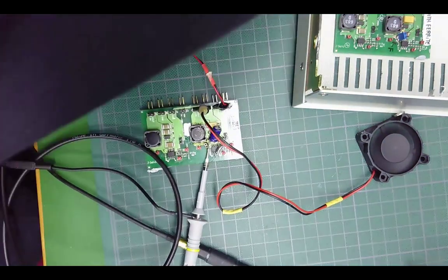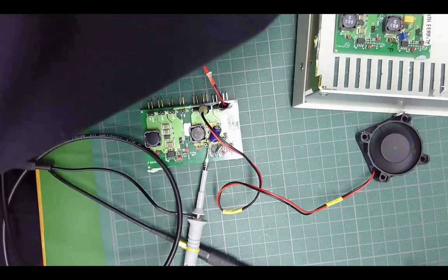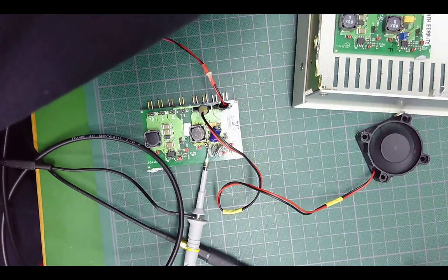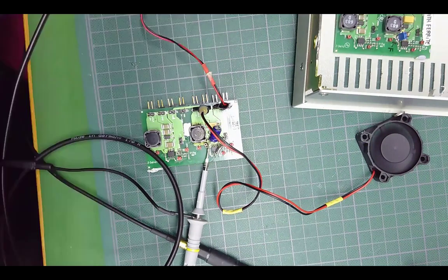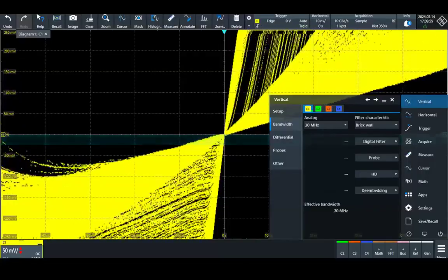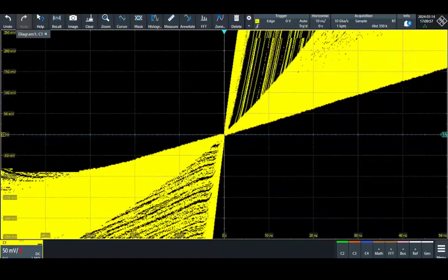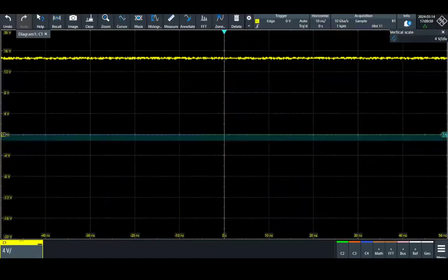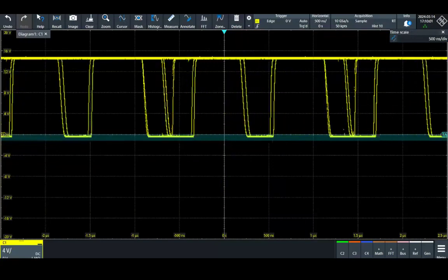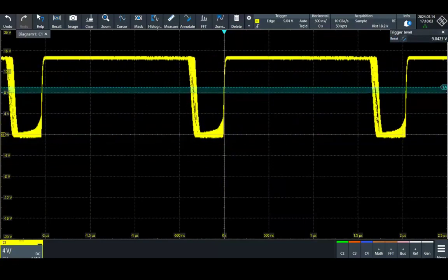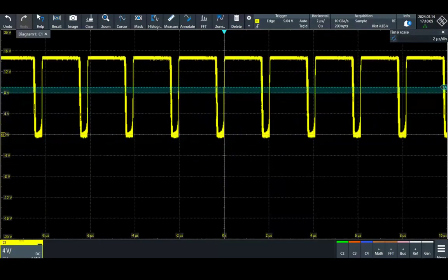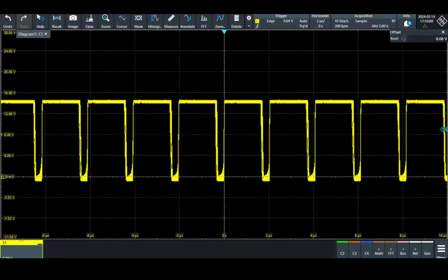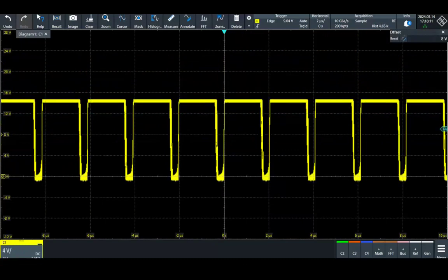But first, consider that my oscilloscope could be, for example, a 20 megahertz oscilloscope. What happens if your oscilloscope is a 20 megahertz oscilloscope? Okay, this is the signal of the switching activity. You see this? We switch in this way, and we adjust the trigger. So this is a typical switching signal in a DC-DC converter. My oscilloscope is now with a bandwidth of 20 megahertz.